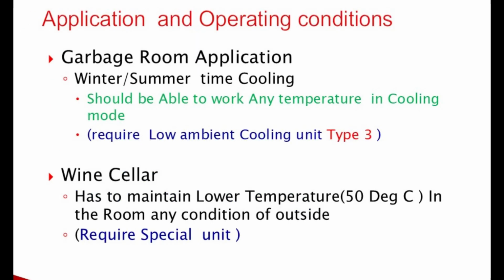The next application is a garbage room. For this type of space, a Type 3 unit is required, that is low ambient cooling unit, as cooling is needed even during winter to reduce odors.